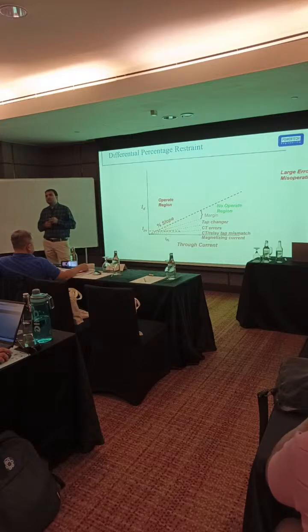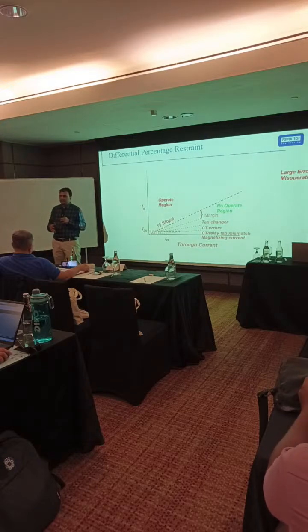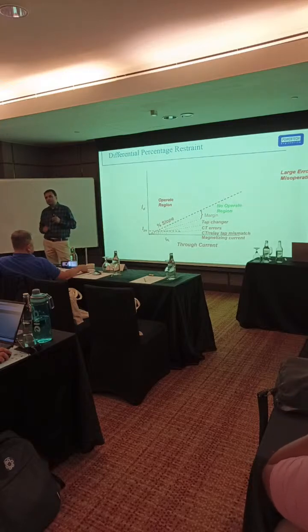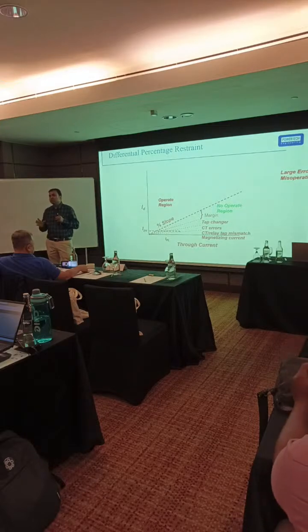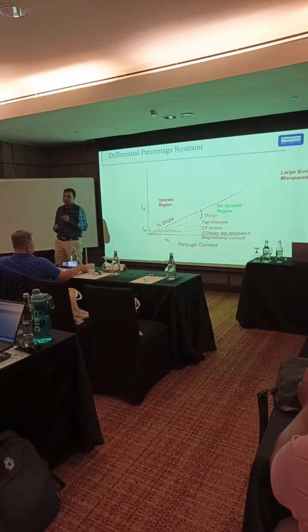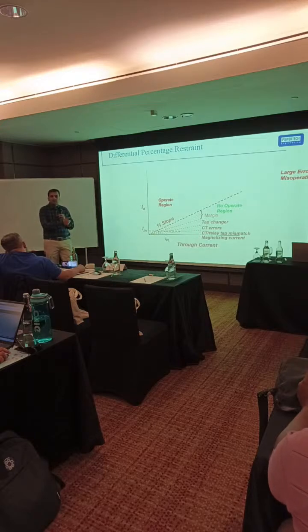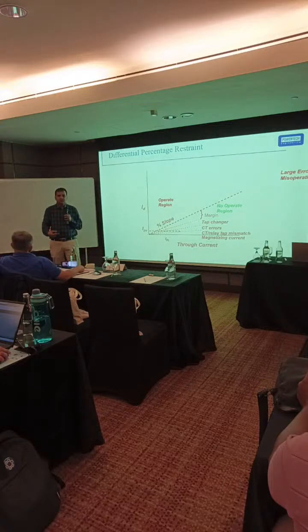And the most common thing I have seen, as you are saying, is that when we are charging, the transformer is tripping. Mostly I have seen it is due to harmonic current. Sometimes we have harmonic blocking in the differential protection, but in SEF also, if you have enabled the SEF protection, during charging neutral current will flow.